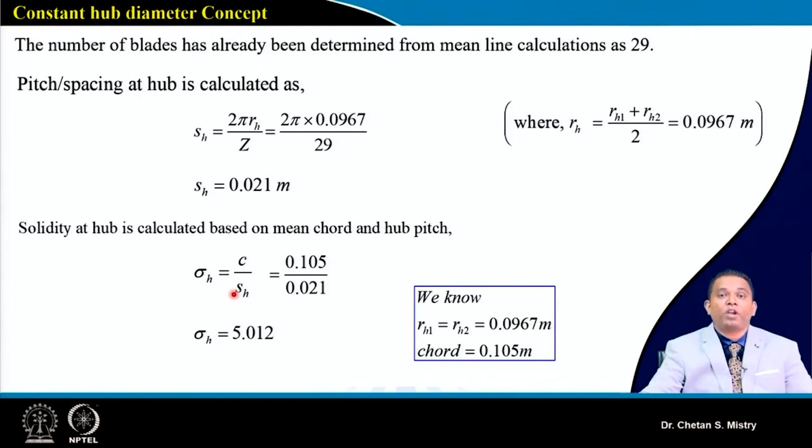Maybe at a design point, maybe at an off-design point, just verify that, and if it is coming as per your expectation, that will be your design. There are certain rules which we need to keep an eye on, but at the same time, superficially there is no such fixed design rule for compressors as well as for fans.